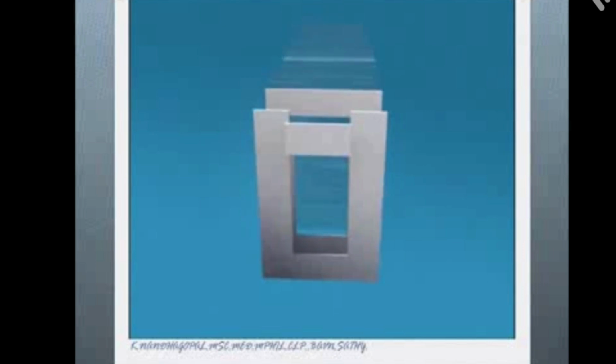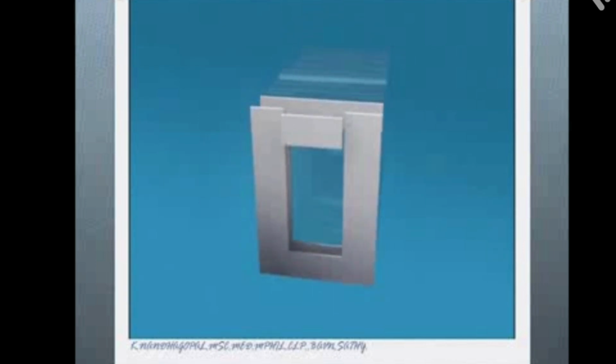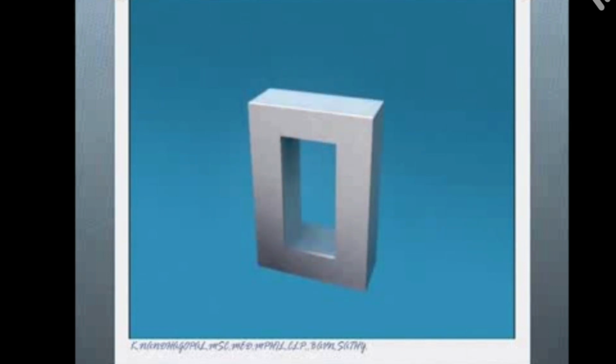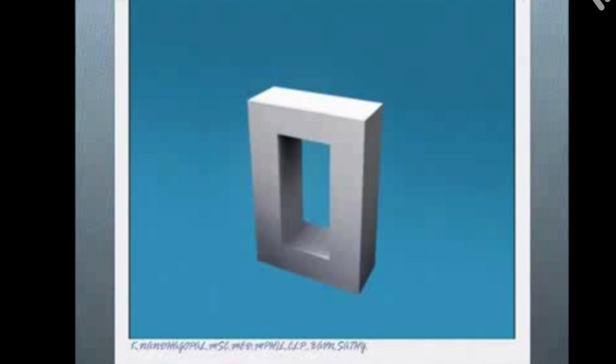These are all metal strips. It is not a bar like a very big piece of metal. It is a sheet. Sheets are combined to form the inner core of the transformer. So this is the transformer core. The coil is wound over the core like this. The primary and secondary coils are wound over this metal. It helps to reduce the eddy current and the flux loss. It's a thin sheet.